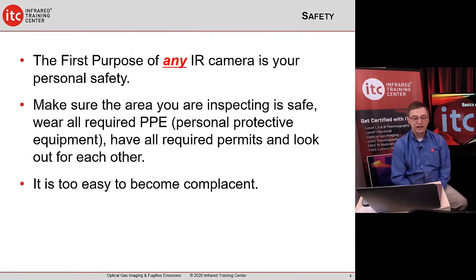Very important, we're starting pretty much all of our presentations now talking about safety. The first purpose of your IR camera is your personal safety. We want you to go home to your families at night and do so nice and healthy and safe. So make sure the area you're inspecting is very safe. One of the easy ways to do this is to make sure that you are wearing all the required personal protective equipment. So whatever is specified for you, including any gas monitors, hard hats, safety shoes, safety training, make sure that is in place before you go out to a job. And it's very easy to become complacent.